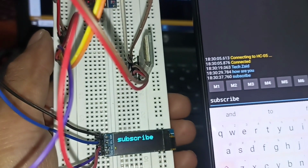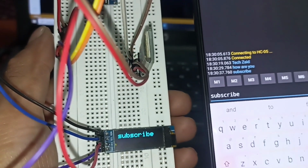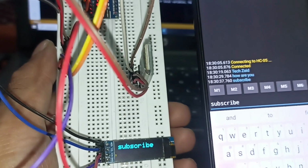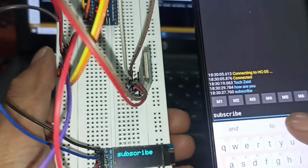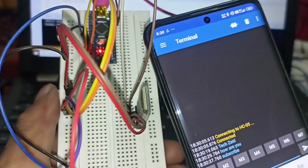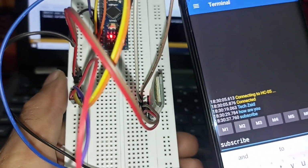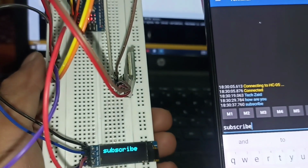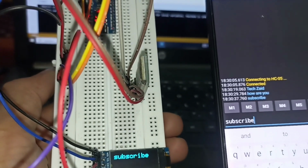So this is the example of UART and I2C communication. In UART communication we are using the RX TX Bluetooth module, and with the help of this I send data from my device to this Arduino Nano using Bluetooth, and then the Arduino Nano displays it on the OLED display using I2C communication. So it's an example of I2C communication.